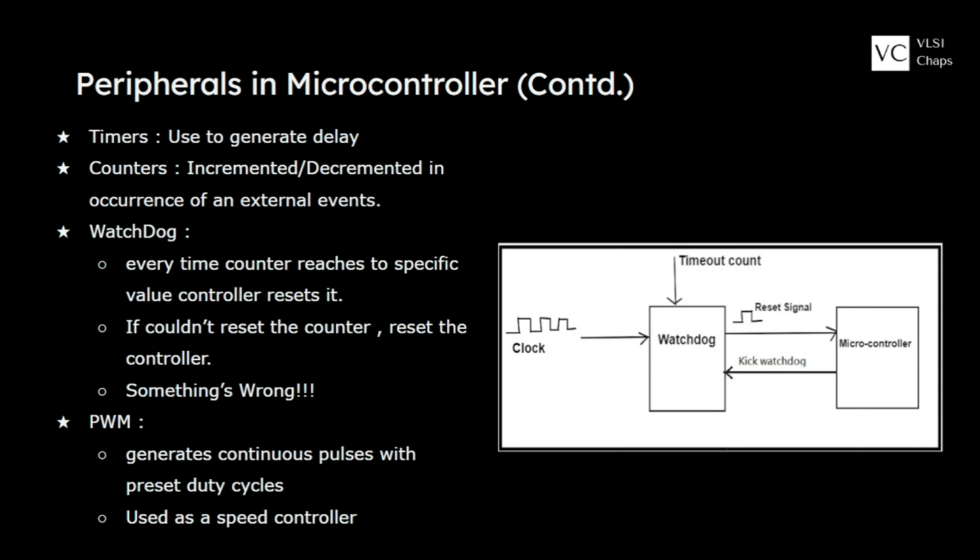It is supposed to do this kicking operation at certain periods of time, but it is not able to do that. And that is how the watchdog will give a reset signal to the microcontroller. So it will reset the whole board and restart its functionality. So this is a very critical and important feature of the controller, which is the watchdog timer, and which is used very widely in all the critical operations.